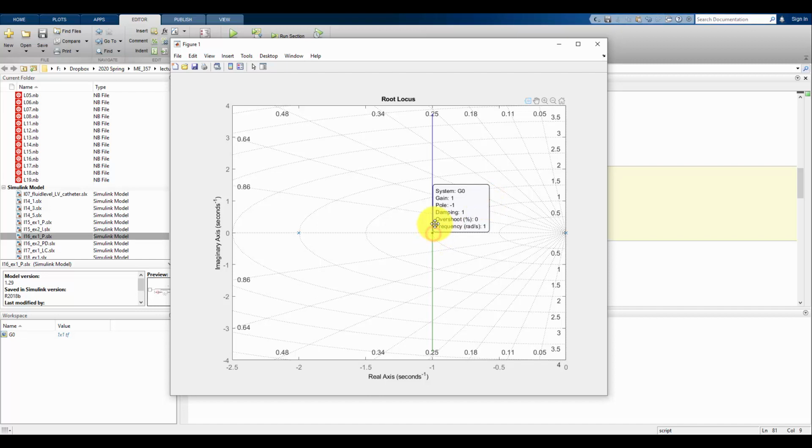All right, so if I have a gain of 1, we see that the poles that we choose from are going to be at -1, which we already know to be true from before. If I drag this a little bit, I'm going up to what happens if k is equal to 2. Well, that puts the poles at -1 plus or minus 1j. Again, keep in mind if I go on the green side, I get where the other pole is, -1 minus 1j. They're in complex conjugate pairs. If I select -1 plus 1j, I've automatically also selected -1 minus 1j.